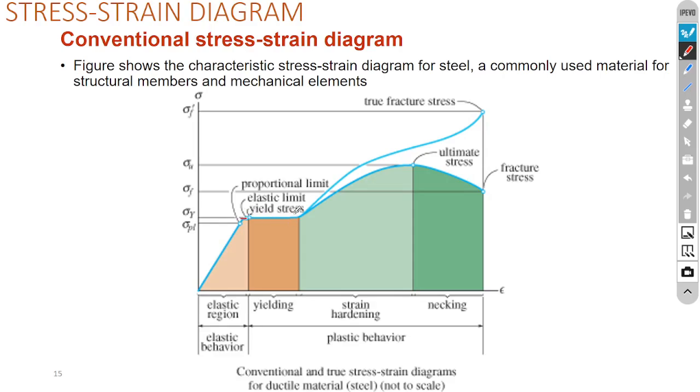After the plastic deformation, after a certain value of the loading, the strength of the material increases. When we plot the stress strain diagram, we see that to be able to increase the strain, the deformation, it is necessary to increase the applied loading, increase the stress. If we increase the applied load, then stress also increases.